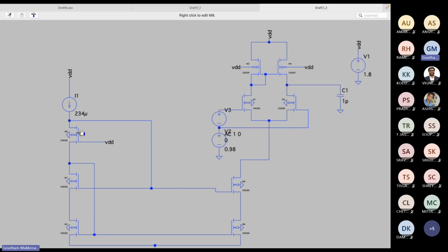What you can do is, you know these voltages. So what is this voltage? 2 overdrives plus VTH. Yes or no? Yes, sir. This is 1 overdrive plus VTH, which is 100 milli plus 500, 600. This is 700. So connect two voltages, 700 millivolts here, 600 millivolts here, and this is connected to 1.8.